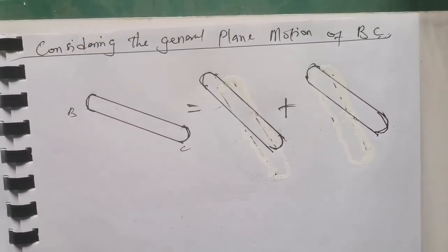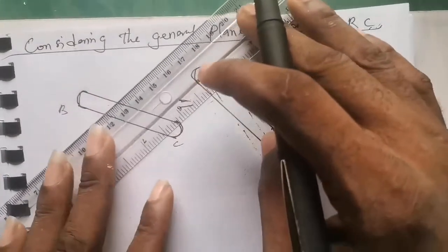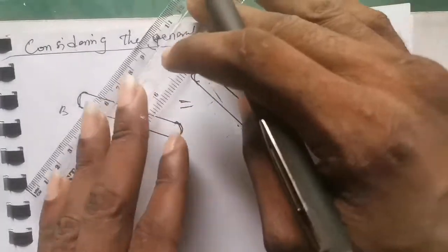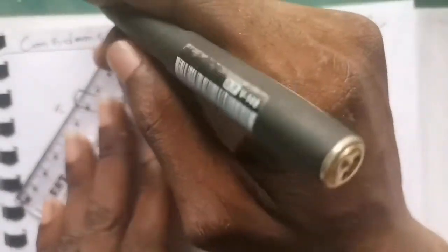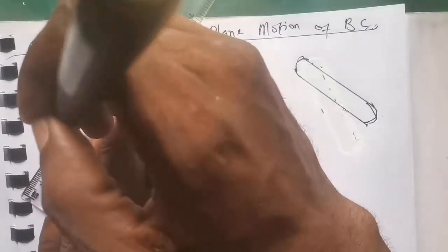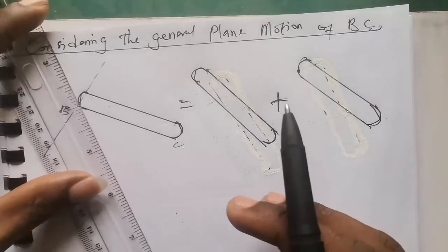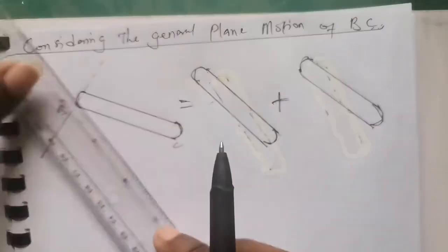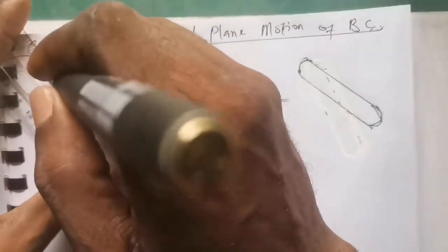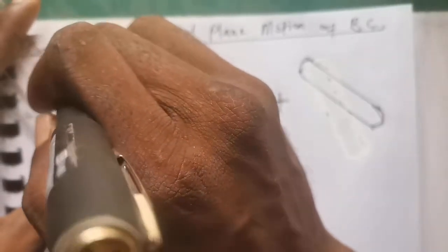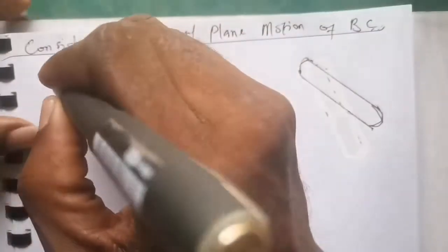We're going to use an inclined line over here just to indicate portion B to C, so we can accurately get the direction of 90 degrees and its inclination on portion BC. So VB is at 90 degrees to this arm AB. So you have VB to be this. All right, so this is 90 degrees to AB.